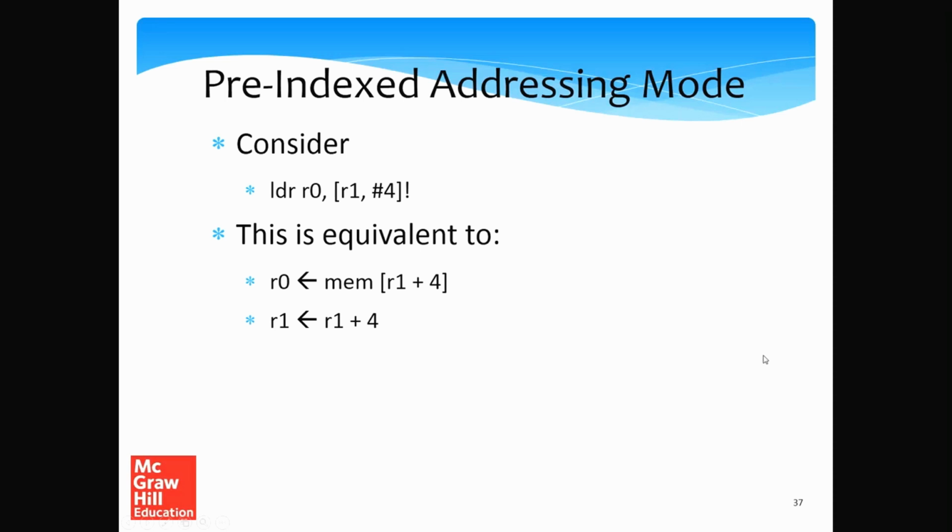Similar to the post-indexed addressing mode, we have a pre-indexing addressing mode as well. Post-indexing is similar to i++ in C and C++. Pre-indexing is similar to ++i, where we increment the value first and then proceed with the current instruction.